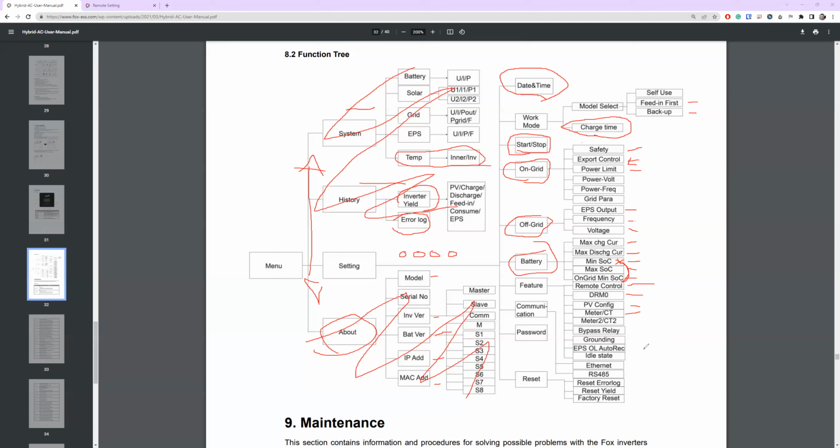So normally a white clip that goes around the brown live, with the arrow facing the grid, so that the inverter can see the incoming power versus the generation, and it's able to do that sort of floating point management, so that the house runs off batteries in the evening and off solar during the day, that it can force charge, and that it understands how much it's consuming versus feeding in.